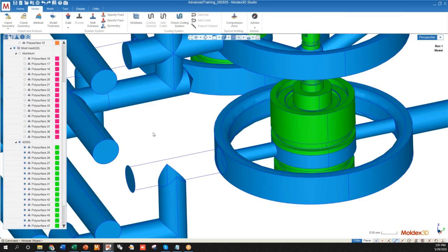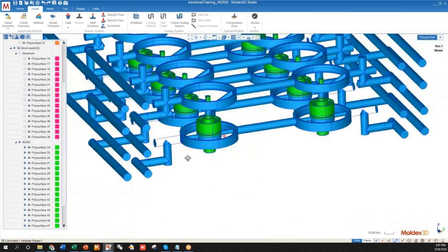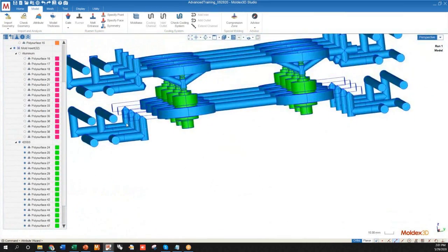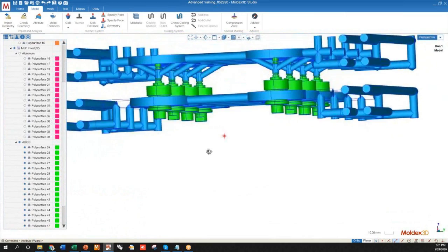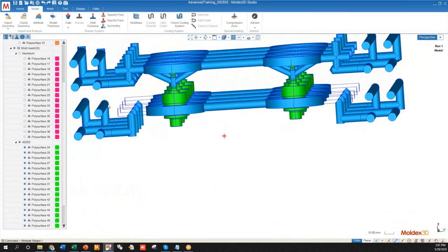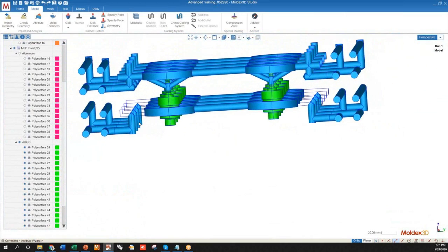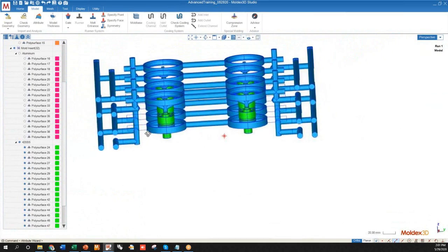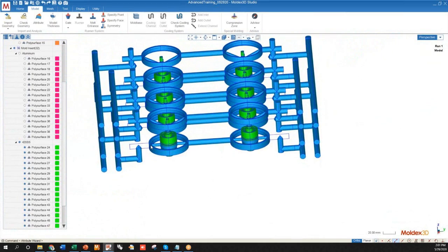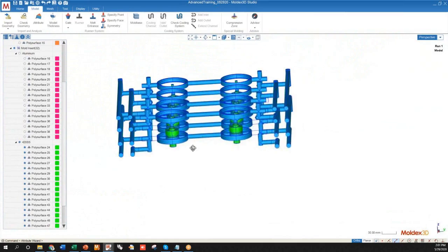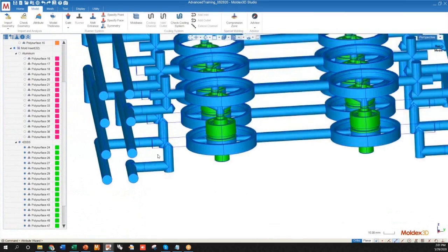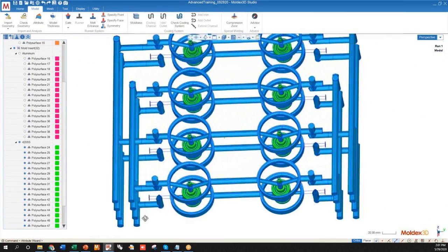It can be a little bit scary sometimes to see this sort of thing happen. To clear this error, you could just run these cooling channels through CAD Doctor, and it would bring those surfaces back as you would expect them. Sometimes this is just a translational error that happens with Moldex3D occasionally. Not very often, but sometimes. So I'm just going to leave them as they are right now. If you do want to run them through CAD Doctor, please feel free to do so.